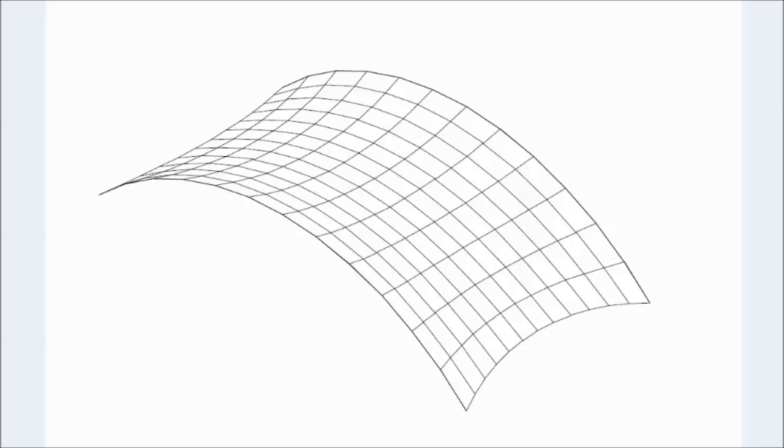The essential starting point for an FEA stress analysis is a good understanding of what results to expect, either from prior experience with similar structures or from a thorough estimate of the stresses. We can then use FEA to get more exact figures for the deflections and stresses, while using our general idea of the expected result as a reality check on those figures.